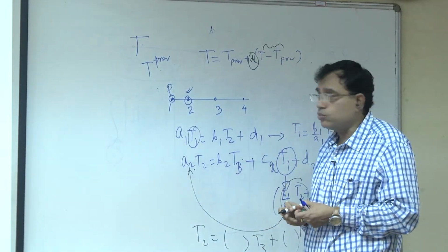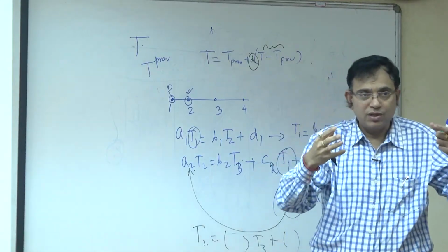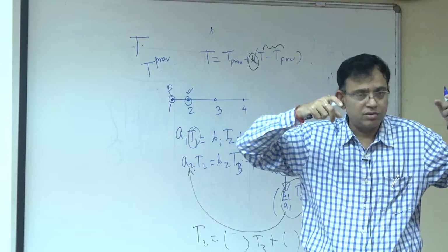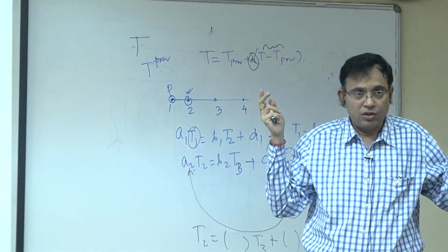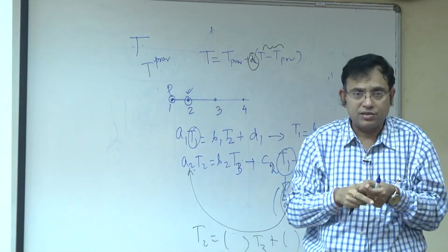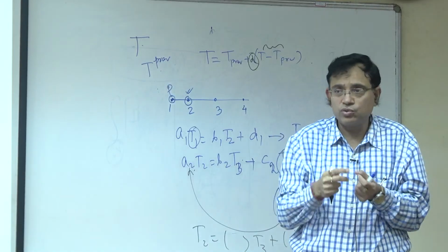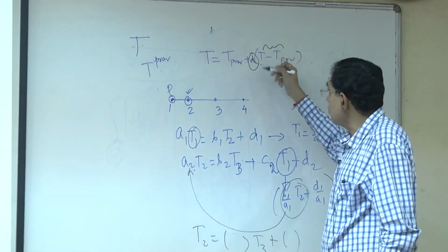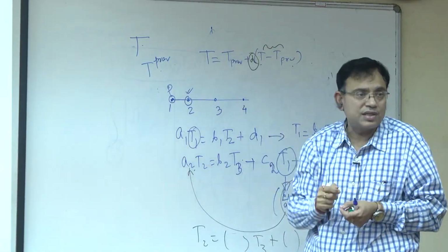So, what I will do is, see, you are starting with a guess and the iteration is moving. Sometimes the iteration is out of your control and the solution is diverging. Many times students say, sir, we are running it but it is diverging. My only recommendation, if everything else goes fine, is to control the change; perhaps with every iteration it is changing too fast. So, this is your change. To control this change you use something between 0 and 1, but typically less than 1.